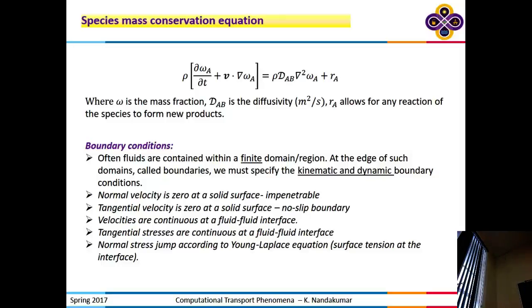Okay, on these walls, I will specify no slip and impenetrable boundary condition. This will be a free surface boundary condition, meaning that there is stress-free boundary condition. There is no velocity, but there is no stress as well. And this droplet is settling, so what should be the velocity at the interface? Will there be a fluid motion?